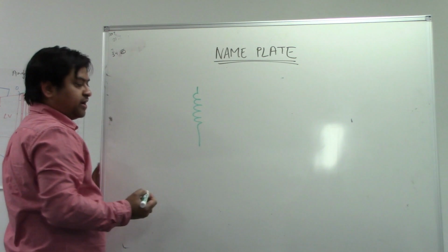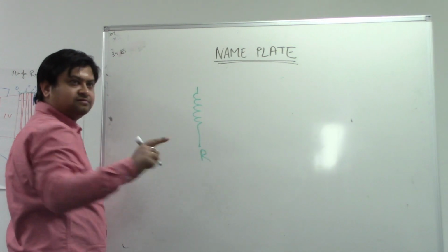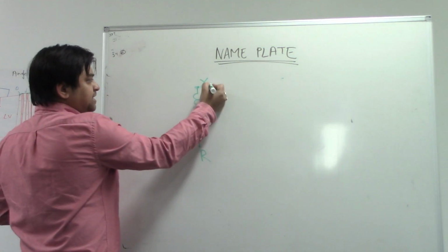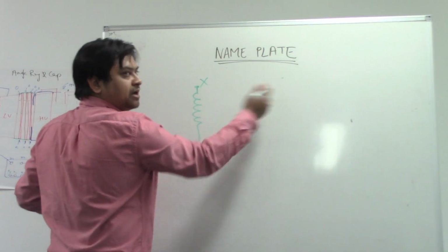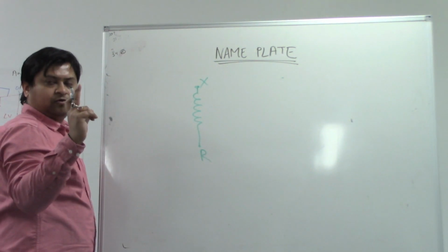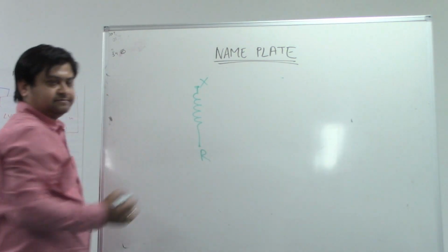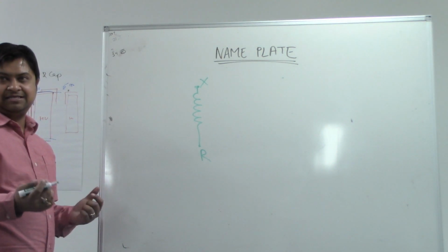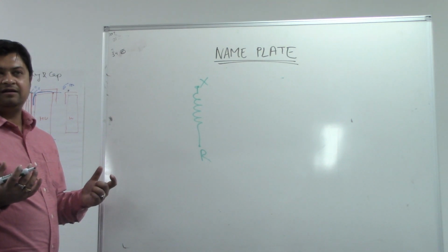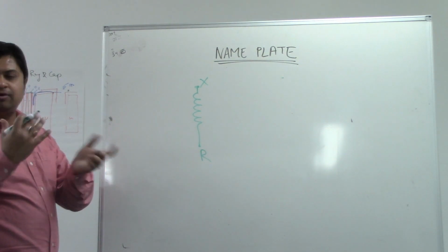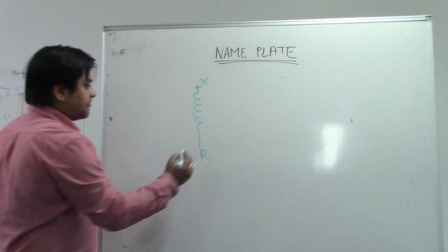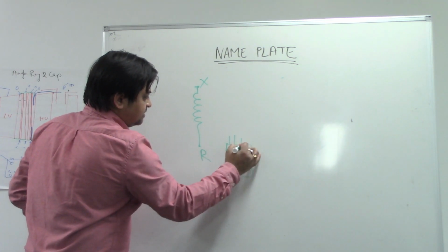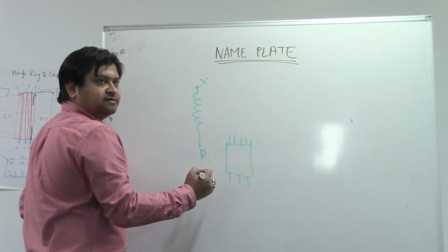Say this is the low voltage winding, right? This is your R. The R comes from the bottom of that, and this is your X. You can name it as X1, X2, X3, right? X1, X2. I'm just showing one phase. This is the R. Now we want to do a plus and minus, similar to the DETC. How do we do it? We have another winding, which is the RB winding. These RB windings are coming like this.